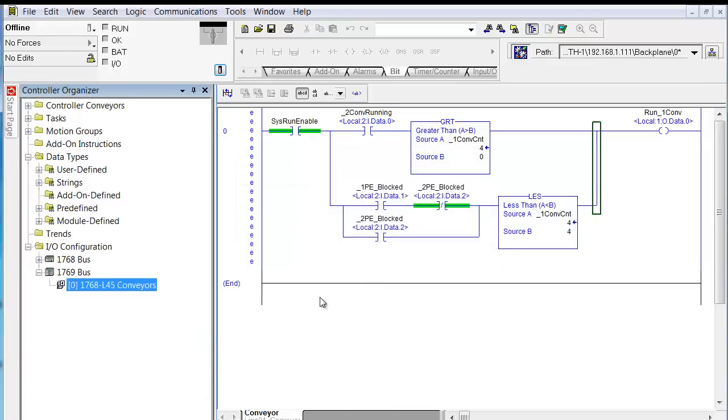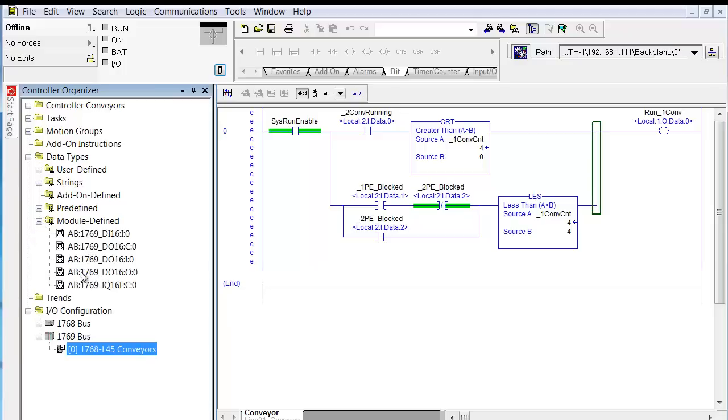Okay. Now we didn't get any more E's, but now all of these I/O tags are in dire straits. None of them are legitimate. Some, as a matter of fact, won't even come back. I didn't do that on purpose, but in my new hardware configuration, when we add I/O modules back in, they're not in the same order that they were in the L35E. So if you were going to mix it up on purpose, you couldn't do a better job than we've done here by accident. So now we've deleted those, and once more, those tags are still there.